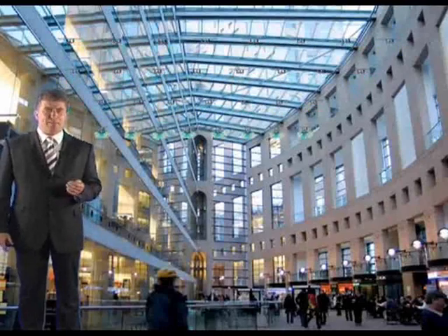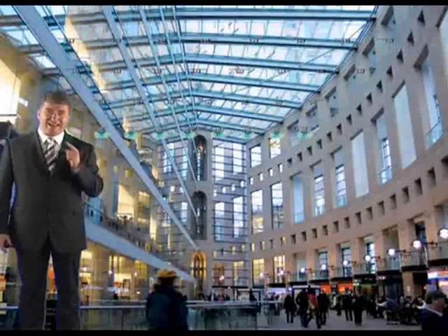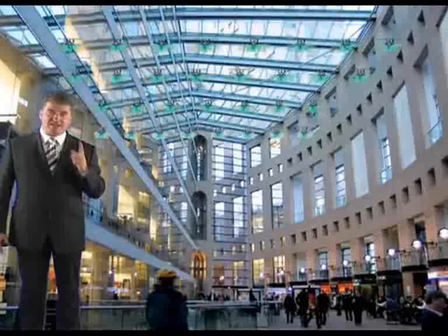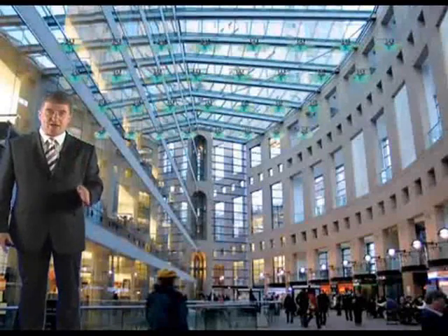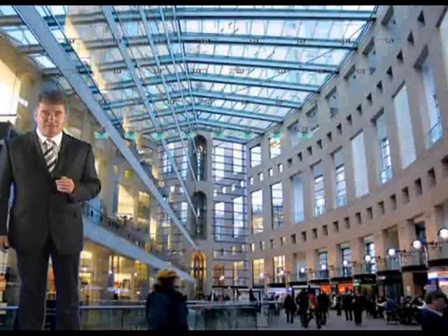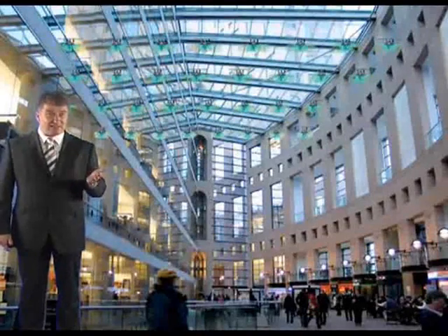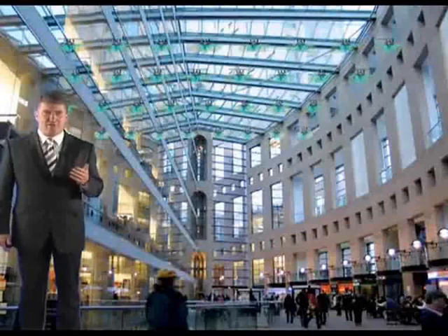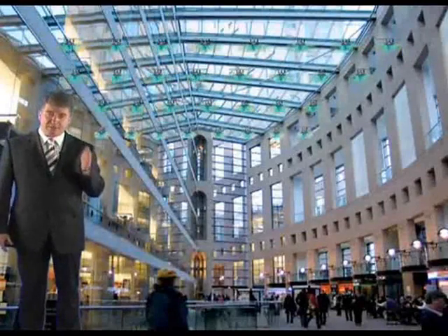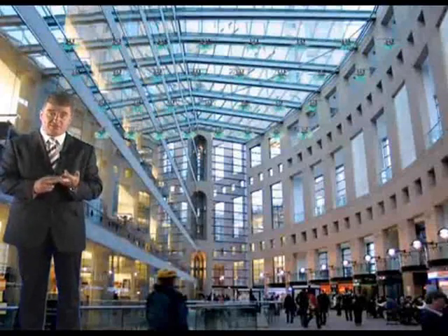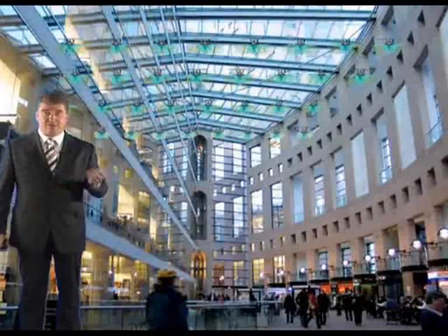Now I want to discuss the impact of installing sprinklers in the atrium itself. So not just in the shops, but in the atrium itself, which is not necessarily the compartment of origin. Sprinklers in compartments off atria, for example in shops, as I said before, are an essential part of the smoke ventilation design in order to prevent a fire growing beyond the design fire size. As I said, fast response sprinklers, 2.5 megawatt fire.